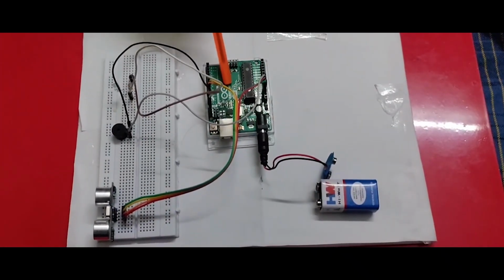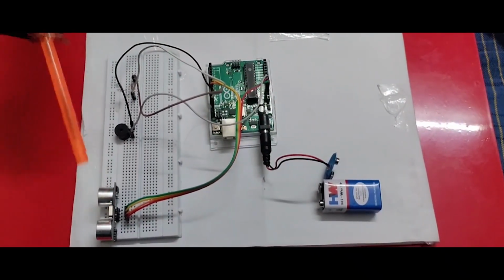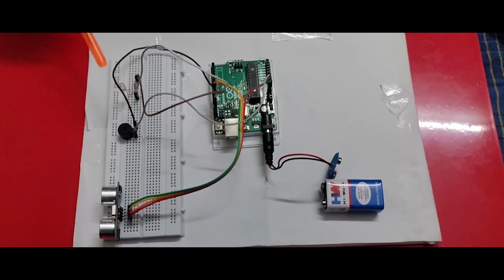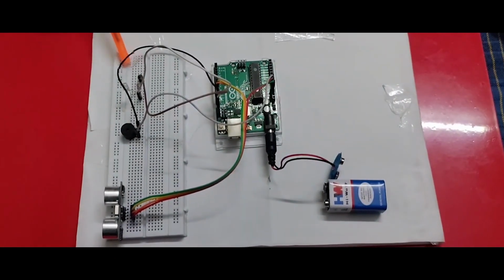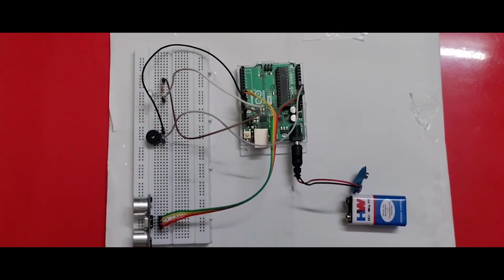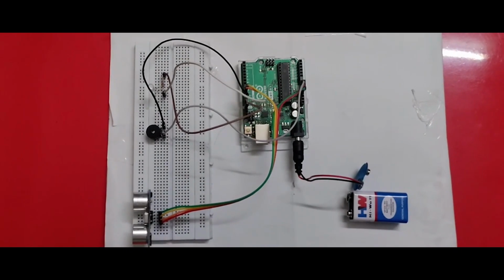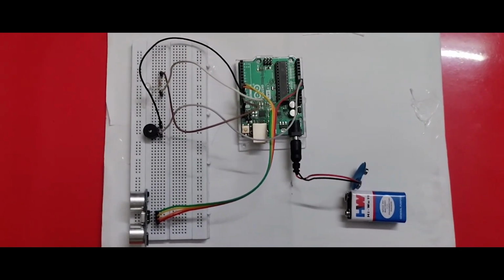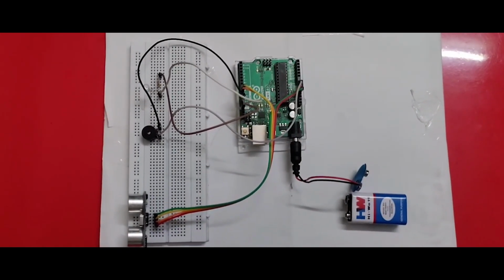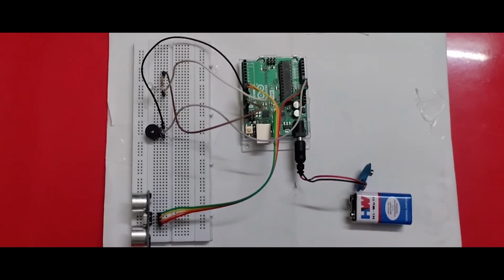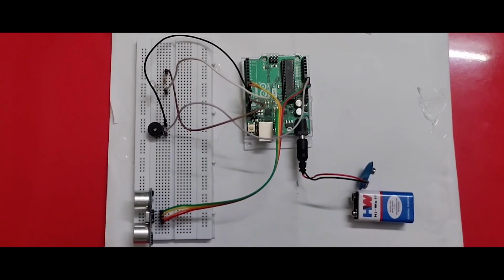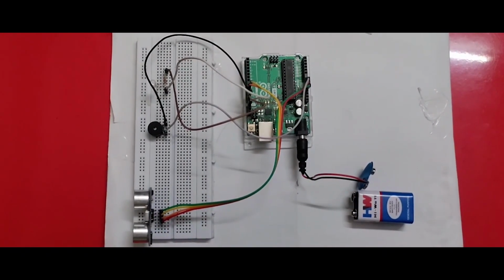The components used are Arduino, ultrasonic sensor, buzzer, LED, 9 volt battery and breadboard. In this, we select a specific range of distance of an object or hand from the sensor. The ultrasonic sensor detects the distance between the door and our hand. When a person places his hand before the sensor, the buzzer makes a sound indicating the arrival of someone at the door. Here we have written a code in the Arduino IDE and dumped it into the Arduino.